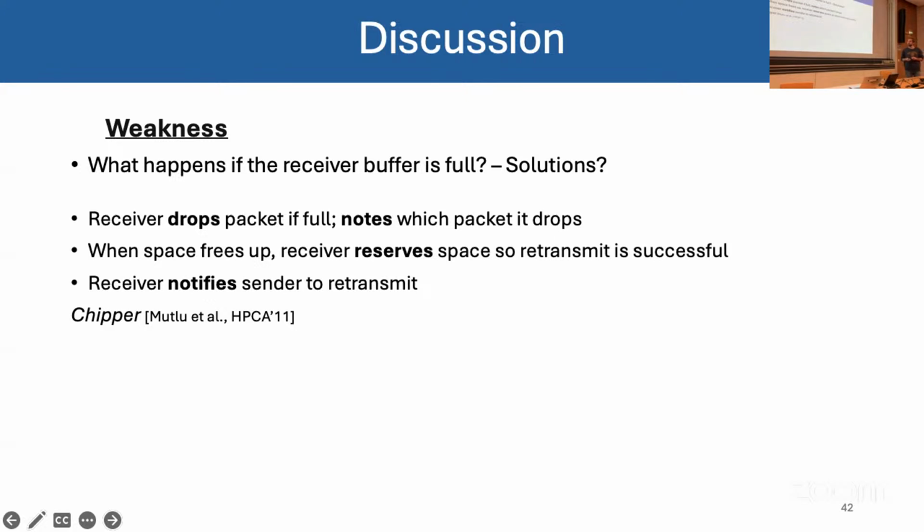And as latency is super important in networks on chip, this approach may work in other computer networks, or in general networks, but here it's not suitable. So it's actually important that we have this optimistic approach that the sender just sends flits into the system, and then just reacts if the flit is actually dropped.